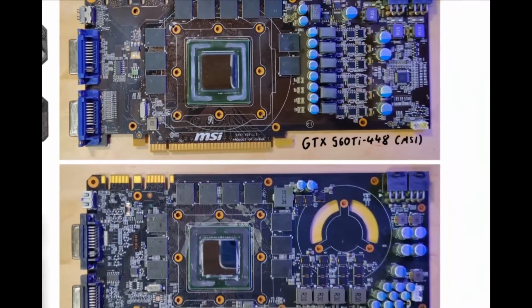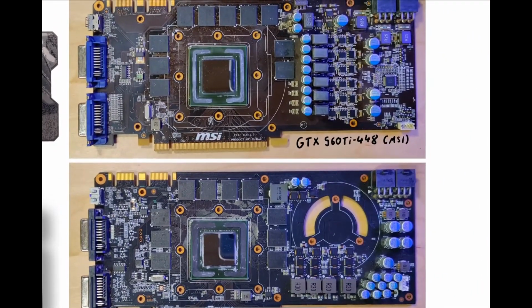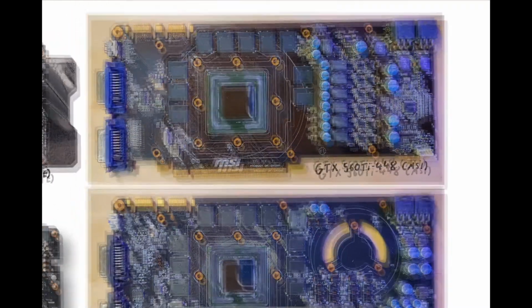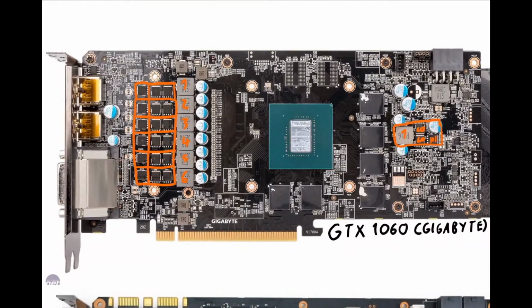This card over here has a very, very low voltage limit compared to this card. Those 2 cards have a very similar GPU. It has the same amount of cores, it just has a different name. They also have the exact same amount of video memory. But the upper card can go to higher voltage because it has a 6 phase instead of a 4, and it is also cooled better. If you cool your MOSFETs better, they will handle more current basically, and yes, keeping them cool will not make them blow up.